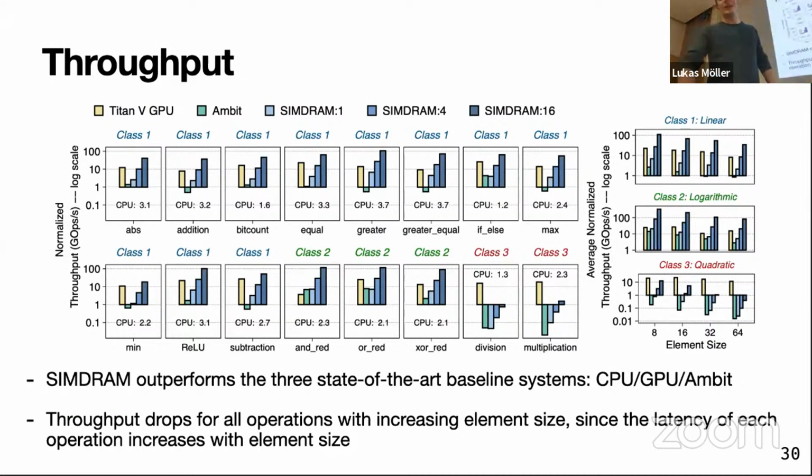Right, the evaluation is entirely simulation-based using the gem5 simulator, and SIMDRAM was compared to an Intel Skylake CPU optimized for AVX-512, and the GPU that was used for evaluation was an NVIDIA Titan V. We also have 3 variants of SIMDRAM compared here. The number after SIMDRAM specifies the number of banks used for computation per channel. Channels usually have 16 banks in this configuration, and this is the number of banks which the memory controller can issue commands to.